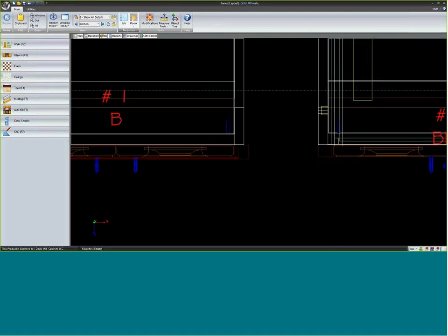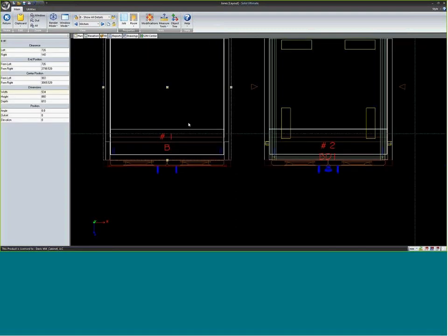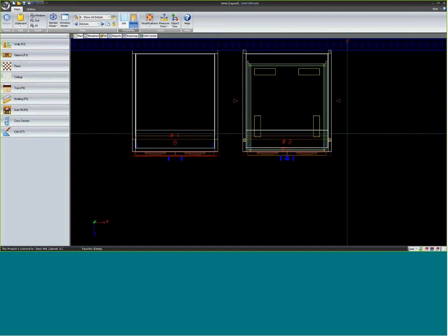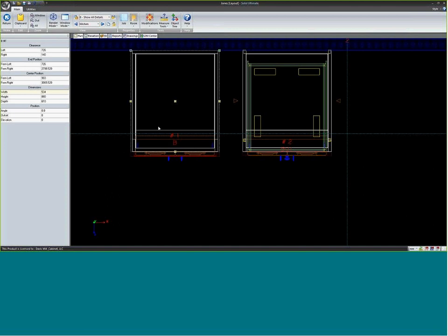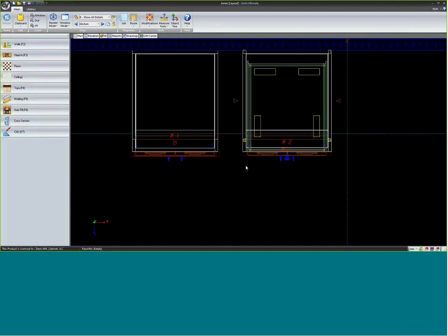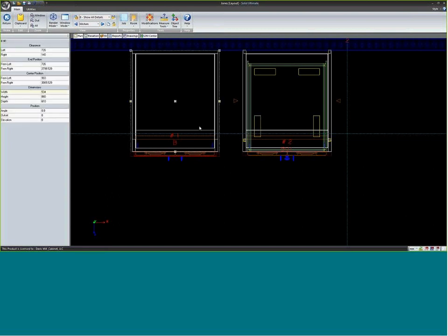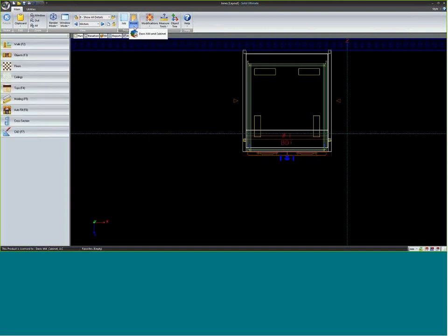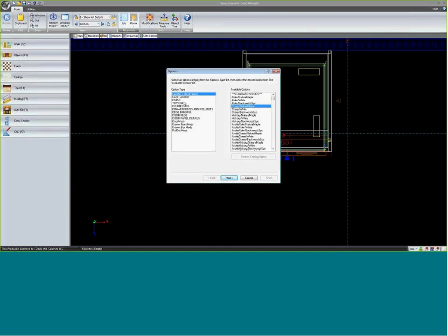The reason for that is this cabinet had an override placed on it. So overrides will overrule anything upstream from it. So you have to be careful if you ever make a cabinet level override and then later go back and make a room level change. Wherever you have overrides, they do not accept the room level changes. Hopefully that makes sense. That's going to be really, really important, and we'll show you this here in a while today when we section doors.